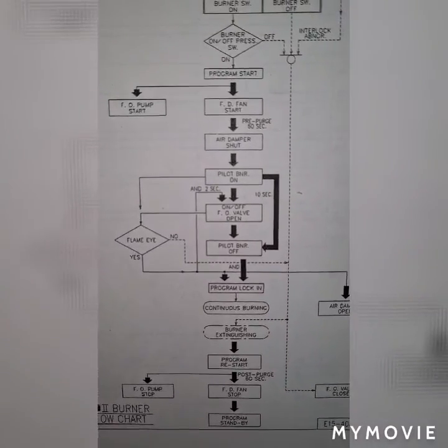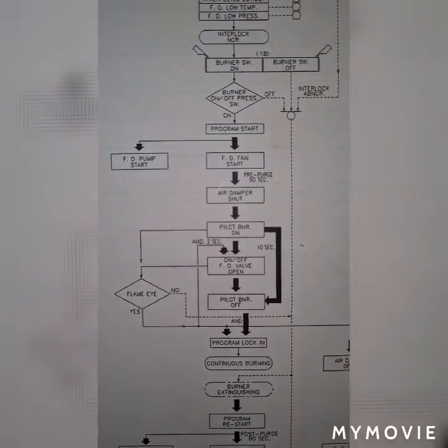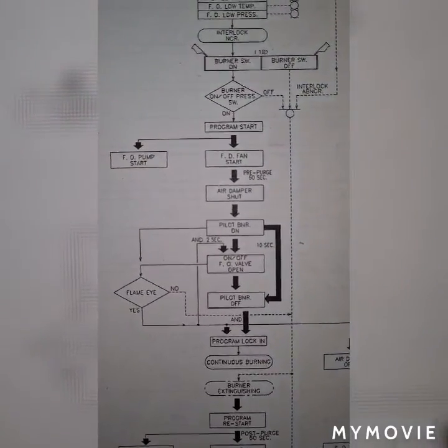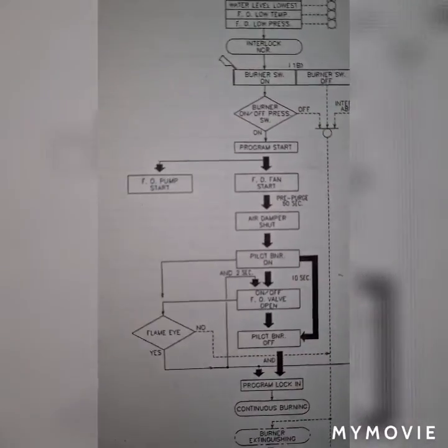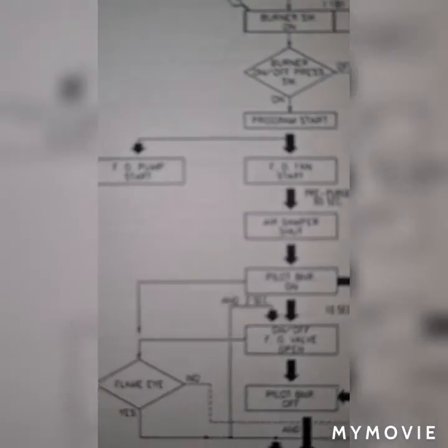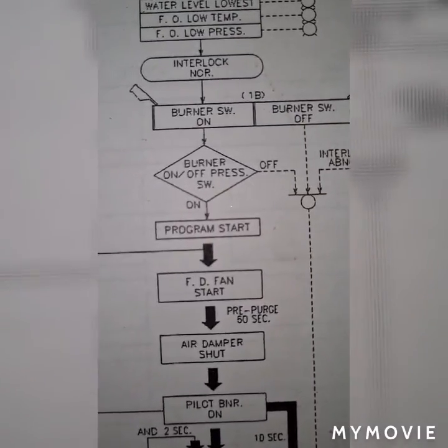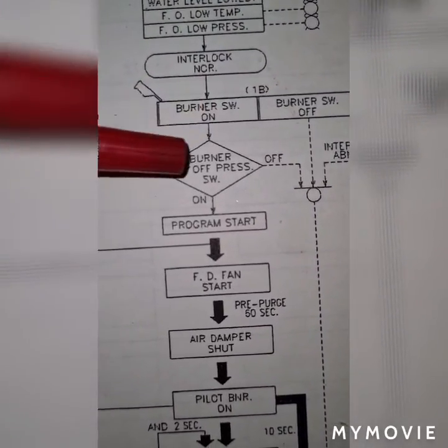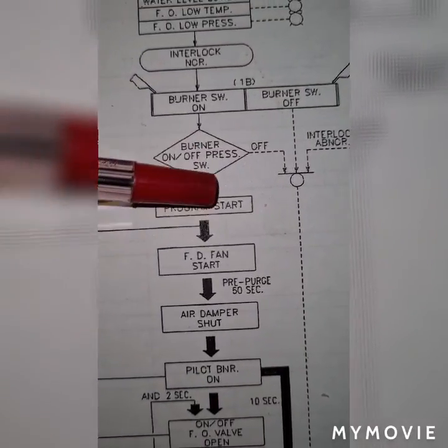My pressure transmitter will detect the lowering of the pressure of my steam. If the steam becomes less than 0.47 megapascal, the boiler pressure burner switch will close and automatically switch on.